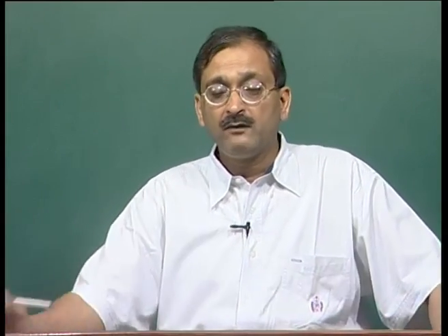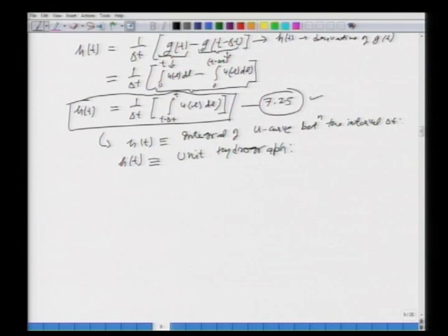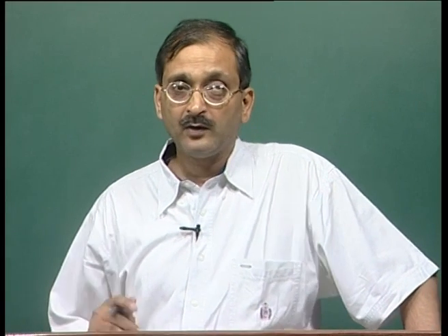So, that is your unit hydrograph, and the unit hydrograph is equal to what? Well, it is nothing but the derivative of your S curve. What is the S curve? The S curve is the summation of the unit hydrograph for a certain duration. But theoretically, this unit hydrograph is nothing but your integral between the limits of t minus delta t to t of your IUH.